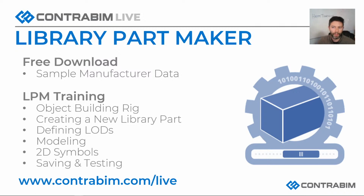So really what we're going to be covering in this training is how we have rigged up the library part maker object building section of our template, as well as some simplified design tools that we've established to grab and assemble objects with. We will create a new library part for our object today. We'll define different levels of detail for both 2D and 3D. We'll go through some different modeling exercises that I think will be fun, and then we'll save and test our object. So with that, let's jump over to Archicad here, and we'll dive into the workflow.